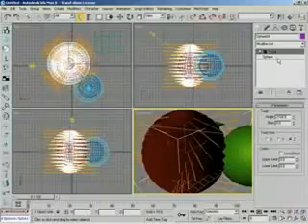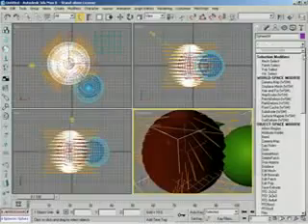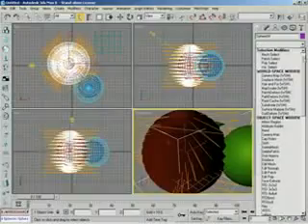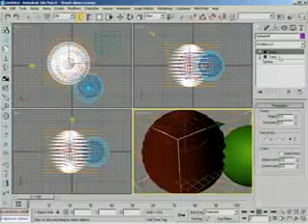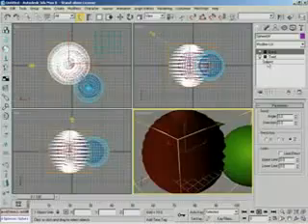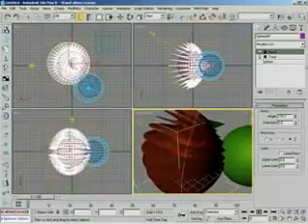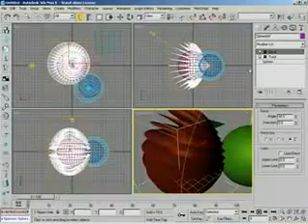Right. You might say that the modifier has been stacked on top of the sphere command. That's awfully fancy. That's absolutely right. And you can continue doing exactly what Bill just said. Stack modifiers. I can say, let's add a bend on top of the twist, where now, here's how you can read the stack. We're going to create a sphere, and with our sphere, we shall twist it. With our twisted sphere, we shall bend it. Cool. So, it's that simple.